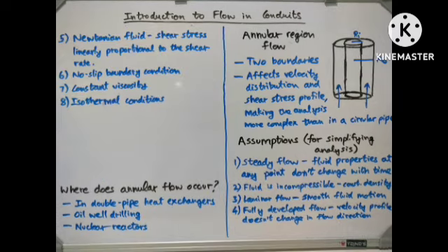Before setting up the problem, we need to establish some assumptions to simplify our analysis, following the logic presented in Transport Phenomena by Bird, Stewart, and Lightfoot. First, we assume steady flow, meaning the fluid properties at any point don't change over time. Second, the fluid is incompressible, so its density remains constant throughout the flow. Third, the flow is laminar, characterized by smooth, orderly fluid motion, typically occurring at lower Reynolds numbers.